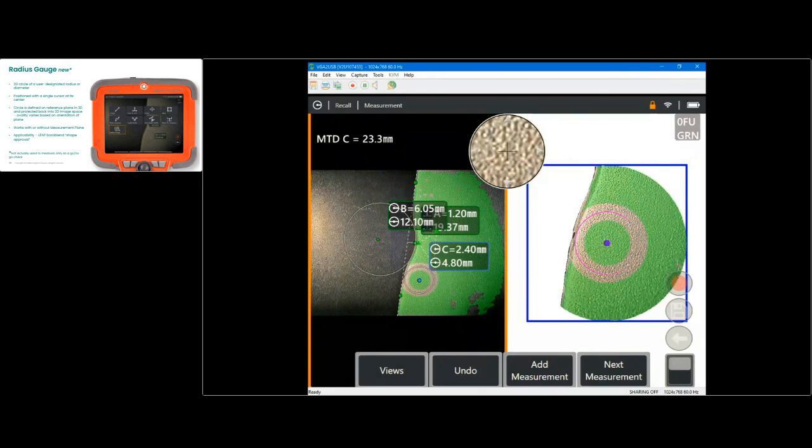So this is an example of an acceptable scallop that exceeds the minimum radii of 5 times and 2 times the depth of the blend, in the center of the blend and all the lead outs here. And I could, but I won't, as it'll make the screen a lot busier, apply a third circle gauge up to the top lead out here.